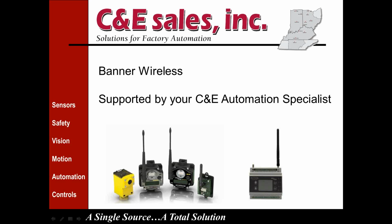Again, life cycle battery is hard to say without knowing what the application is. Most of the battery powered nodes have the ability to go into kind of a hibernate mode and then power up from time to time and send that information. When they're powered up, then they kind of go back to sleep. So it's highly based on frequency. Signal strength, is it 900 megahertz or is it a 2.4 gigahertz, which I didn't talk about a lot. The 2.4 actually allows the batteries to last longer because it takes less power to transmit.